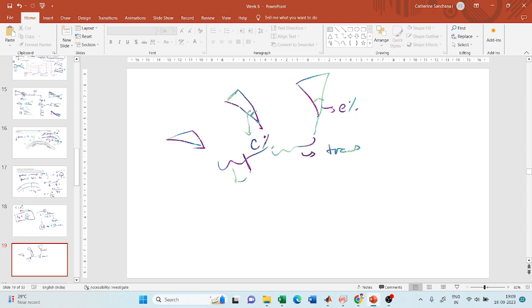So you have to find out at what rate I should increase the slope of the super elevation. That is called the rate of change of super elevation along the length. As I move along the length of the transition curve, at what rate should I increase this slope? I should keep on increasing, right? So here it was C and here it will be E. At what rate should I increase the super elevation height? So that is called the rate of change of super elevation.